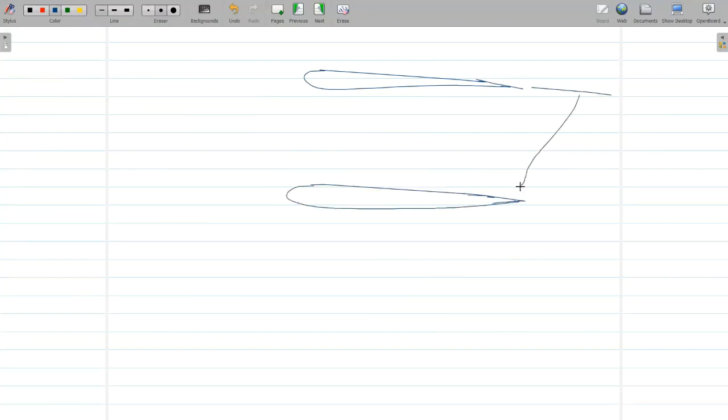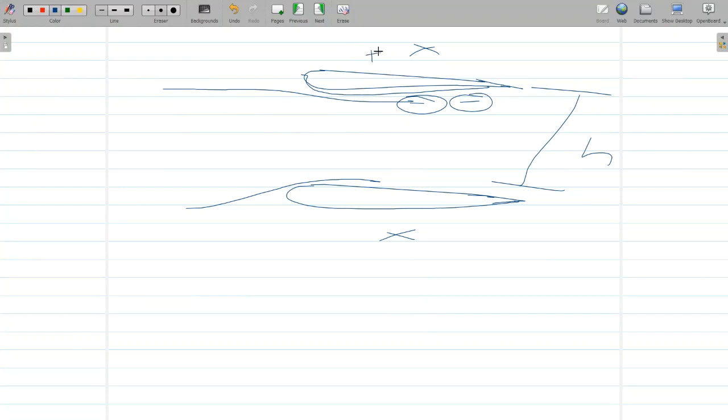So let me explain. Let's say I have kept the airfoils in this way, airfoil B and airfoil A. And mind you, they are at the same angle of attack. So let's say flow is moving in these locations, right? In these locations, you can ignore these two locations. So here you can see that this is the top surface of the airfoil. So this is the location with negative pressure difference, and this is the region with positive pressure difference, right? So this curved surface is the region where your air will in fact accelerate and the pressure will be lower.